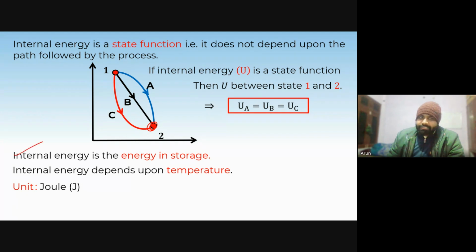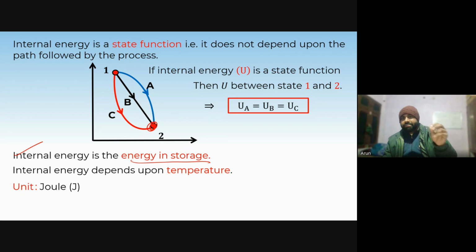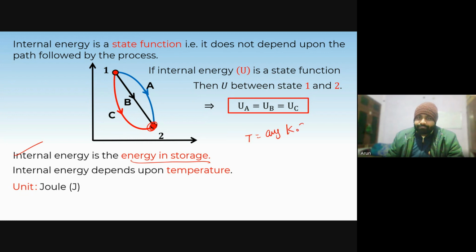So internal energy is the energy in storage. Internal energy depends upon the temperature. Why? Because when I was teaching you the concept of temperature, I told you that temperature is the average kinetic energy. So if you raise or decrease the temperature, the kinetic energy will change. So we can say that internal energy will change. That is why internal energy depends on the temperature.